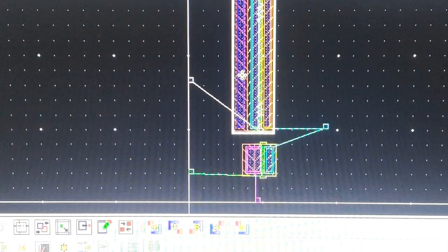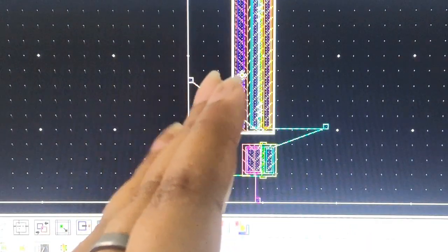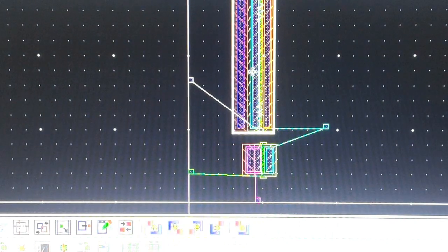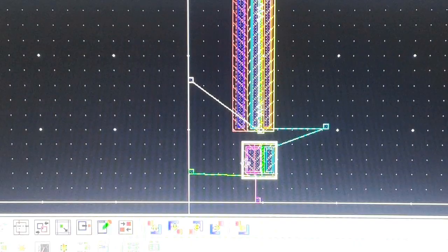on which side is it? It is on this side. So that means this part, this light blue color outline, is going to be a source. Okay, and this side is the drain. This side is the drain, this is the source, right? Now this source has to be connected to VDD, so it will get a little bit messy.